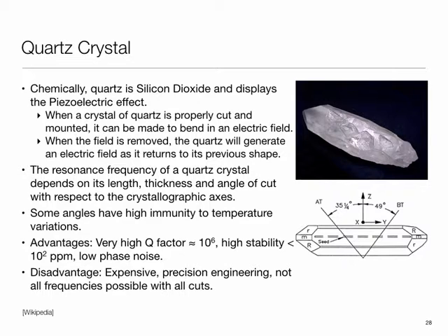They are a very stable source with good characteristics, good phase noise, that is the jitter on the edges is less, and they generate frequencies in a very narrow range, so you can pick them out and amplify. They require very precise machining. Most of these things are now manufactured in East Asia. I don't think there's much local manufacturing happening.